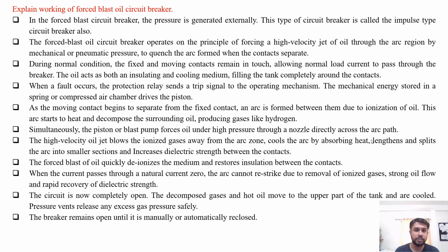During the normal condition, the fixed and moving contacts remain in touch like this, allowing the normal load current to pass through the breaker contacts. The oil acts as both an insulating medium as well as the arc quenching or cooling medium, filling the tank completely around the contacts. Now when a fault occurs, the protection relay sends a trip signal to the operating mechanism. The mechanical energy stored in the spring or the compressed air chamber drives the piston in downward motion.